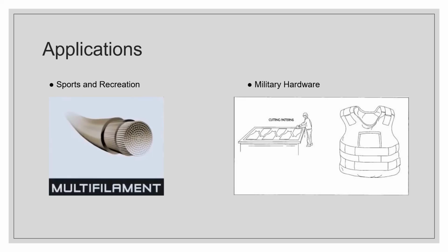In military applications, Kevlar provides a suitable material for the production of bulletproof shielding and apparel for military personnel. For Kevlar vests, large spools of the woven Kevlar fabric are laid out to be cut according to the desired shape and size. Several layers of the same template are cut and stacked together, usually with a minimum of 8 layers, all the way up to 25, depending on the desired protection.